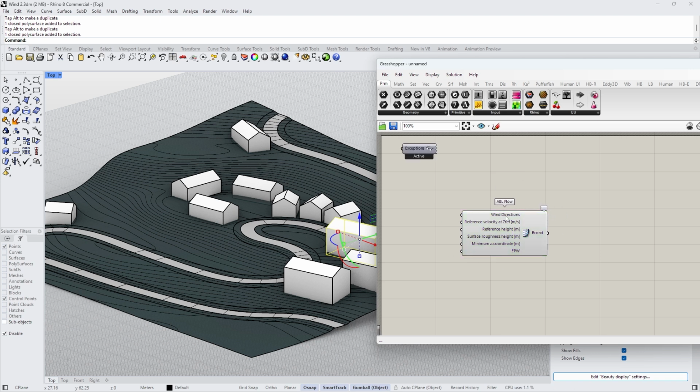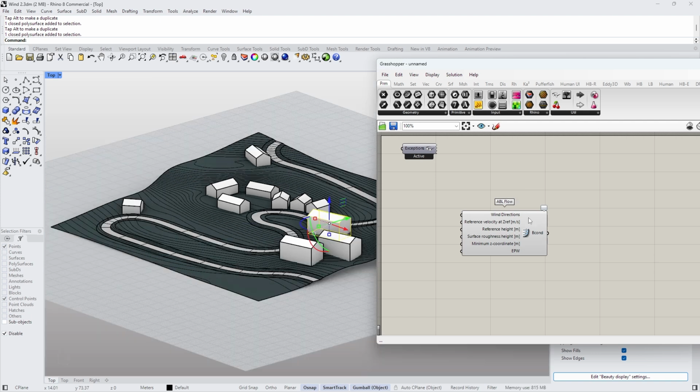Okay, what's in here? Wind direction. So basically what it does, it sets up your domain, the wind tunnel. So the wind tunnel will need all this information. Now this is where most people don't get it right. Don't just use defaults. Try to understand really all the inputs.